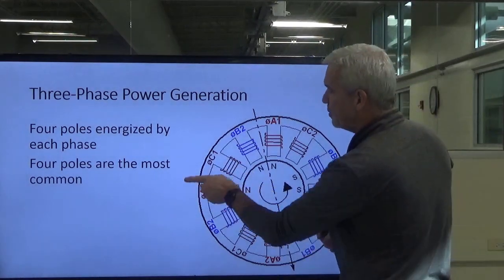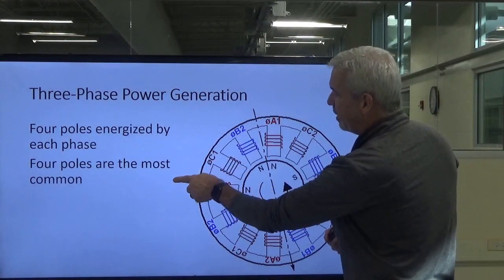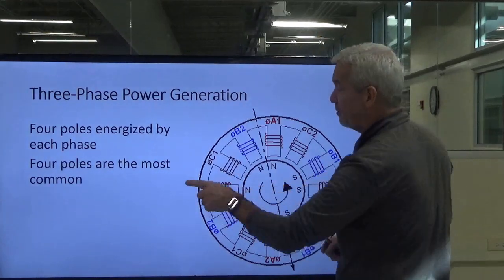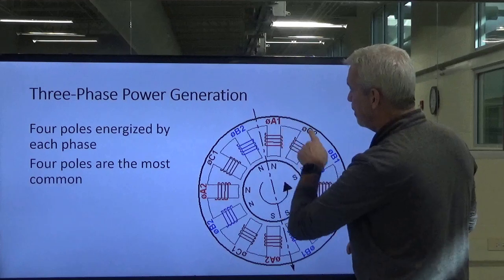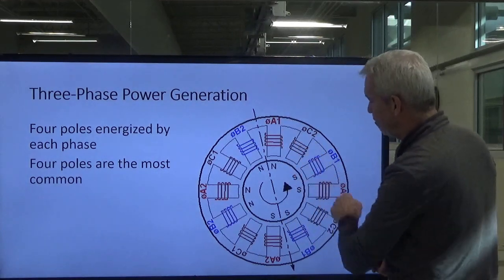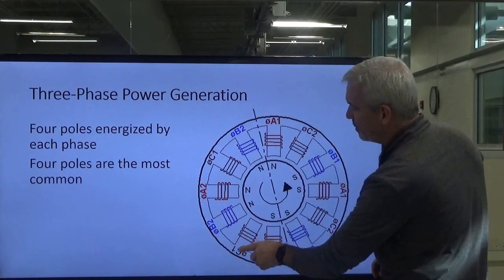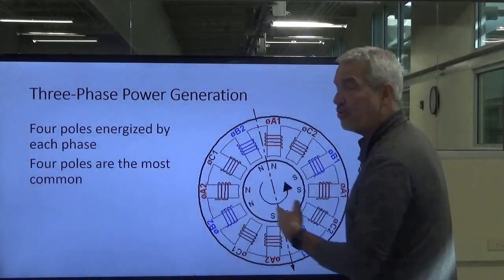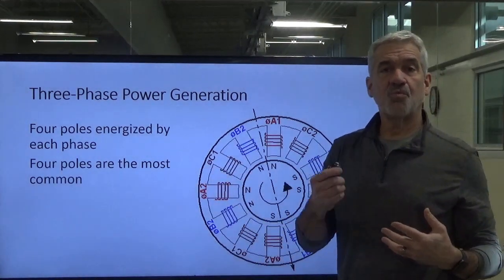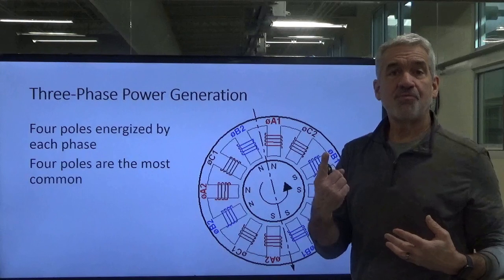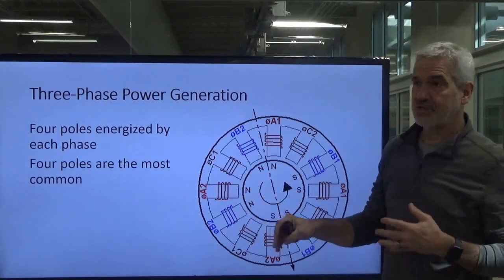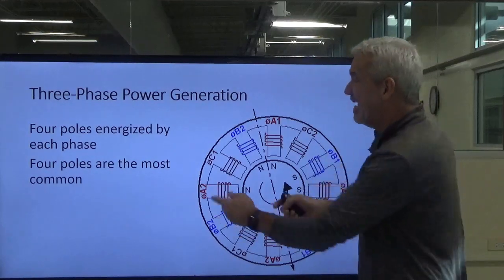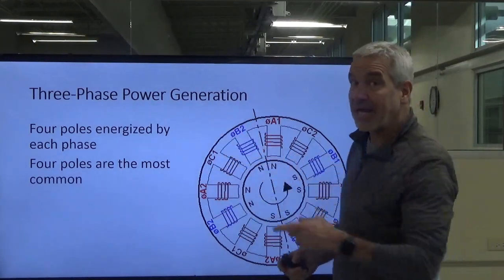Then you've got another set of windings, okay, that will hook to another phase of your voltage, and it'll come in as one wire and go around and around the C2 pole, the C2 pole, the C2 pole over here, and the C1 back here, and it comes back out. Remember what I said? A coil is a winding that is one piece of wire with a beginning and an end. There's nothing magic that's going on inside here. It's not connected in all kinds of different crazy ways. It's one piece of wire coming in and going back out, okay?